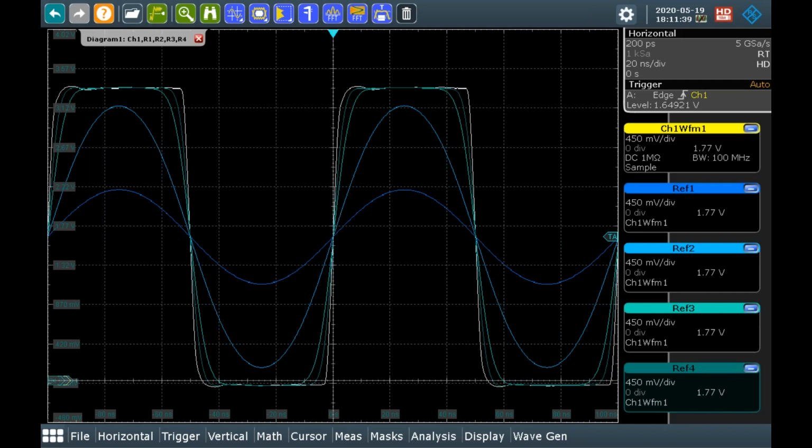The only difference here is that a 1 mega ohm connection that a probe typically has is perhaps 200 volts peak versus in the 50 ohm cabled connection, you're at 5 volts. So one of the more common ways that people can damage the front ends of oscilloscopes is by leaving a scope in 50 ohms and putting a higher voltage signal in. Even something like a 12-volt battery could damage the front end. So it's something to be careful about, but cabling in, if you've got good cables, that's the easiest way to get the full bandwidth out of your scope.